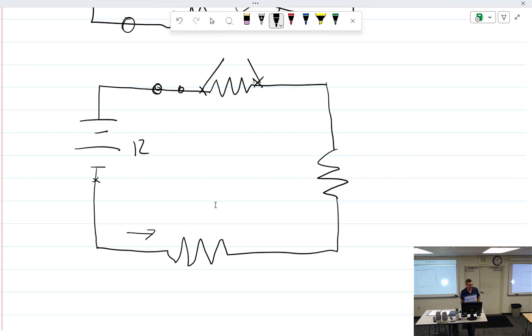It'll bend the needle on the reader, yeah, but not if it's digital, right? So it doesn't matter if it says +6 or -6. The difference is 6. It only matters on the analog because the meter doesn't go backwards. If I'm using a digital meter, I pay no attention to which way my leads are going. If I'm not troubleshooting something that could be potentially backwards, I don't care. Or if I do care, I just look at the meter, see it's -6, so I got the things backwards. 6 is 6. That's the way I look at it.